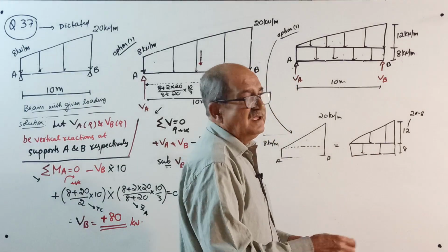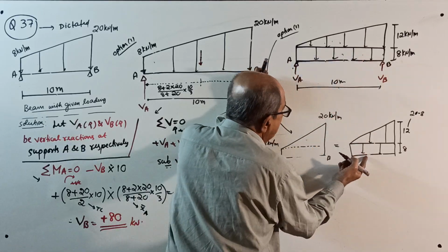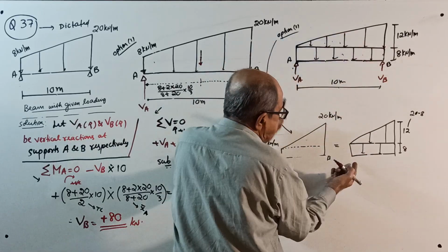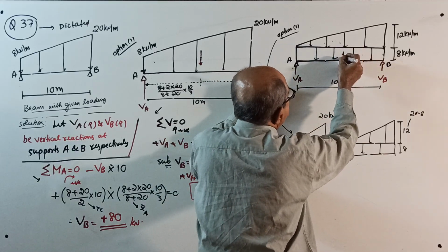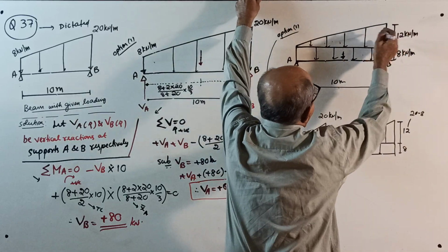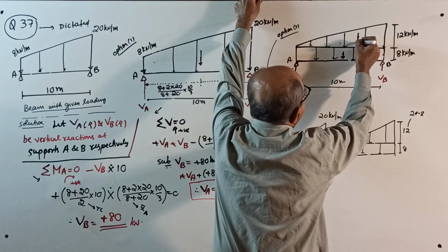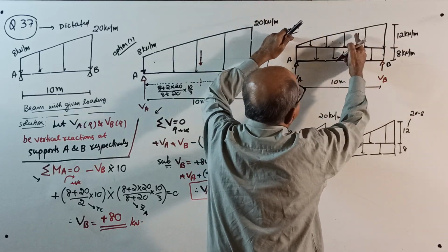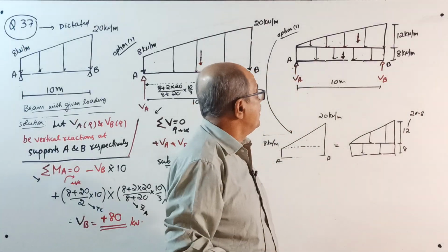Now, see here. For rectangle, resultant force. Now after this one, write this sketch neatly. See, resultant load will pass here to centroid, exactly center. For uniformly varying load, resultant load will be somewhere here. That will be from here 2/3 of 10. That I won't write. Okay, now make a note.